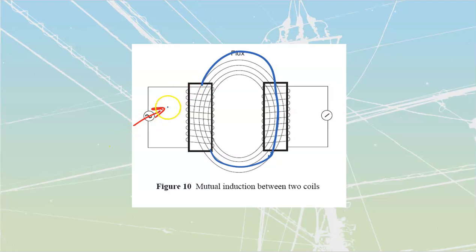So over here, as I increase my amount of current, I'm going to see an expanding amount of magnetic fields. Those magnetic fields are going to hit this core over here. That's where they're going to get attracted to. And then they're going to be expanding inside of here and cutting out through those conductors on the outside. As they cut out through those conductors, we've got everything that we need to establish voltage, right? EG is equal to BLV.